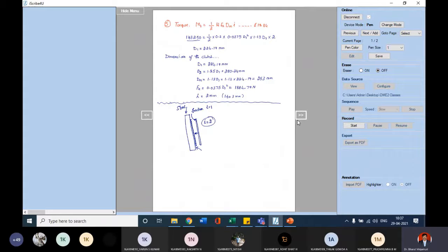But for a single plate clutch, by default you don't worry about this much, because I is equal to 2 should be the right value. We design assuming both the sides are effective. What is the difference? The difference is only in the dimensions in this equation, equation number 5. If this value is 1, you will get half of this diameter, that is, the size of the clutch will reduce slightly. That is the only difference. Other than that, nothing will change.